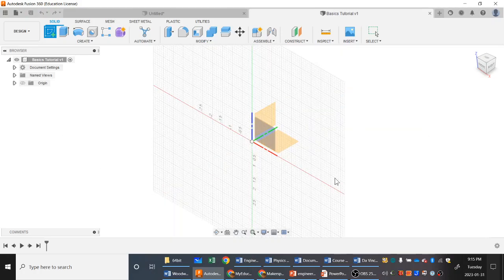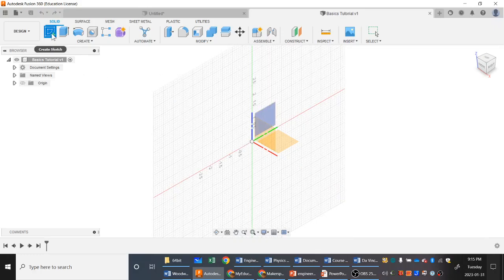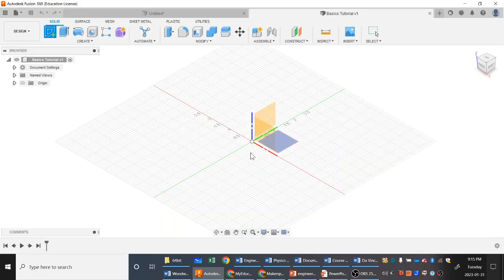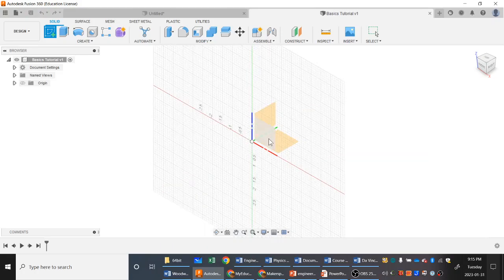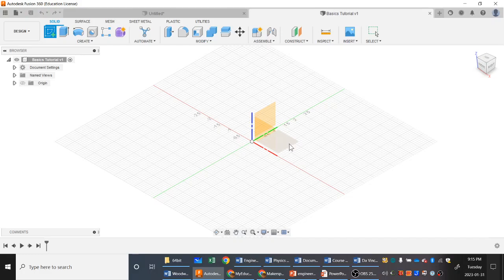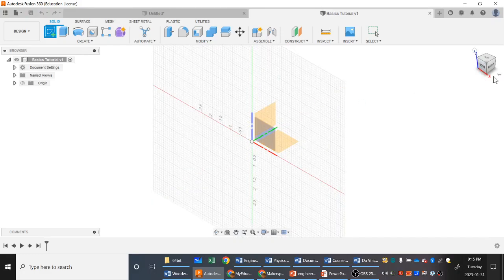Remember, this is a 3D modeling program, but it all begins with a 2D drawing. So what we're going to do is pick a surface to sketch on. As soon as I picked Create a Sketch, I was presented with the origin for my sketch, and these things which are called planes. There's vertical, and there's a plane from above, and a back plane here, and they're all lined up with this thing called the view cube over here, X, Y, and Z directions.